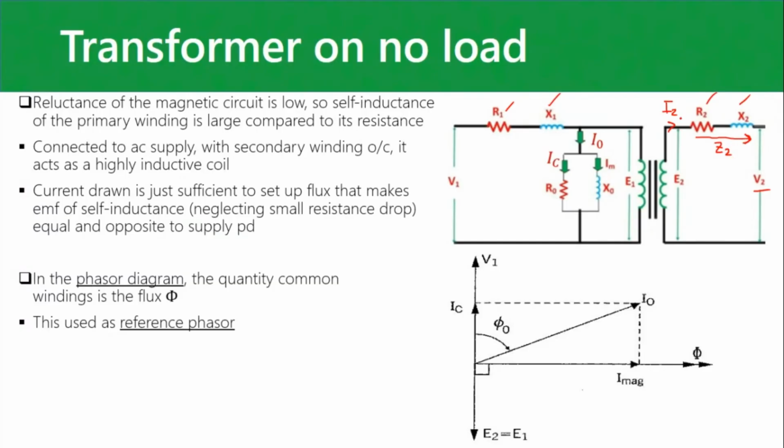So if you've got I2 flowing through Z2, then you get a volt drop across Z2. V2, the terminal voltage, is no longer equal to E2. It will equal E2 when you're on no load, but now if you connect this through a load like that, ZL, you get I2 flowing through the internal impedance, and the terminal voltage is going to be different.